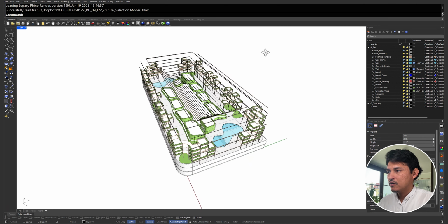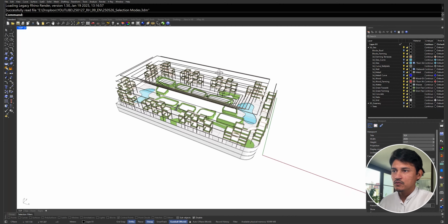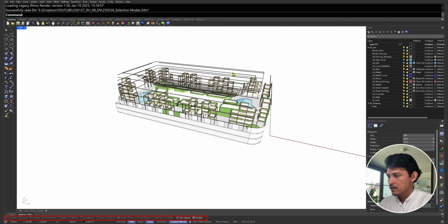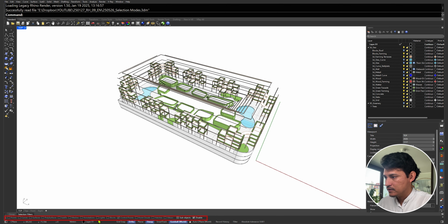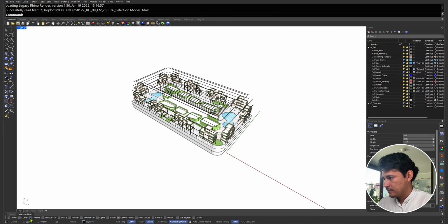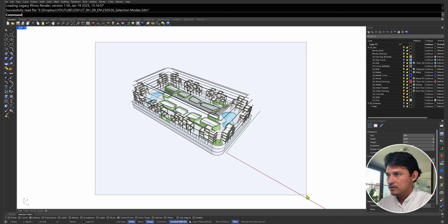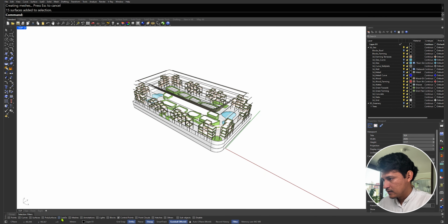So let's continue now, and I have this other file where I want to show you the types of selection you have in Rhino. If you look at the lower side of your screen, you have this large tab that says selection filters. Usually it's disabled, but once you uncheck the box disabled, then you can start using it. And it's very simple. If I check the little box where it says surfaces and I go over my screen with the mouse, then I will be selecting only the surfaces. And the same would happen if I select any of these other elements.